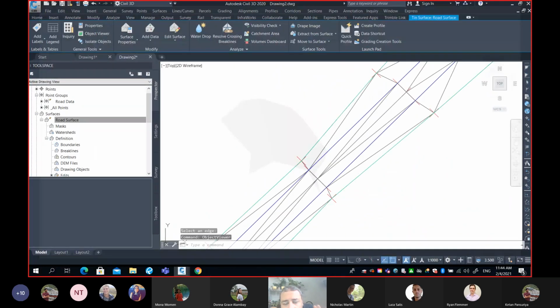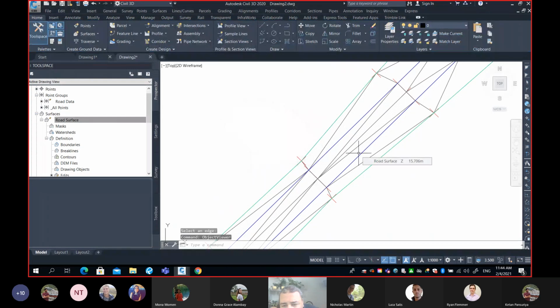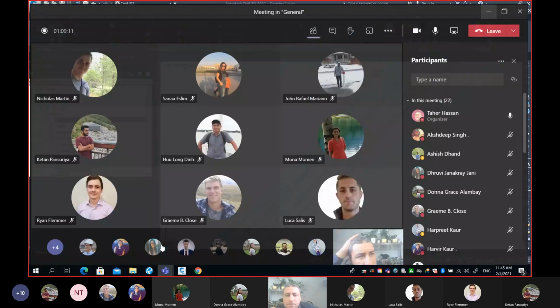So in today's class, you learned two methods. One is a straightforward kind of blind thing. Once you're able to draw the break line, you can add them to the surface definition, while the other one needs some experience on picking which line you need to swap. My recommendation for you is use break line, because the other one is tricky, and sometimes forever they keep swapping edges and they don't converge. They don't know which one to change. Okay, any question for today before we say goodbye?